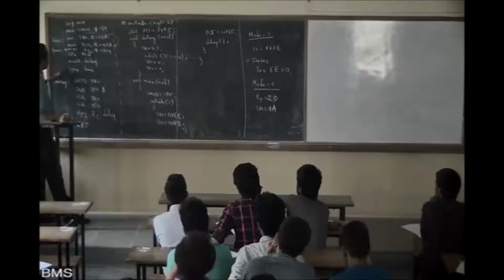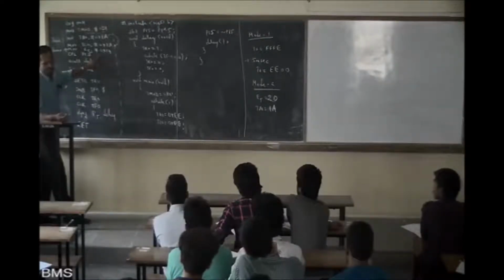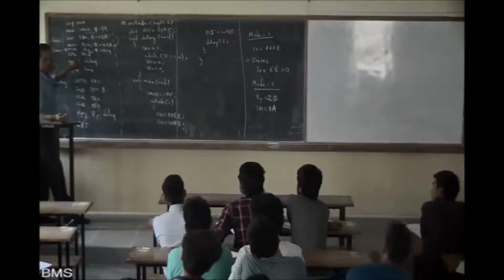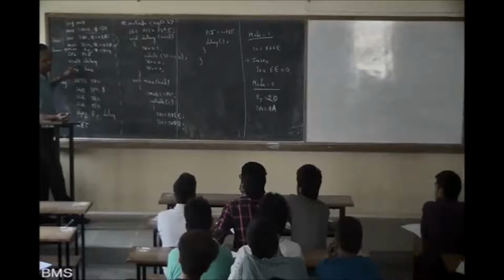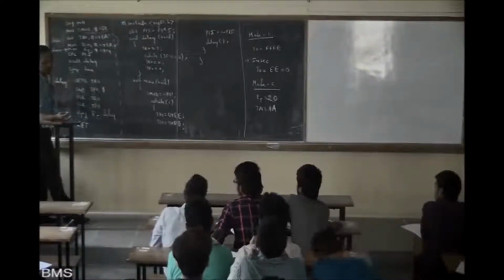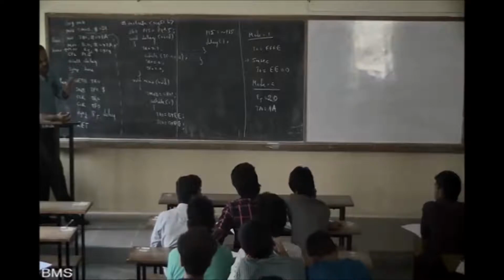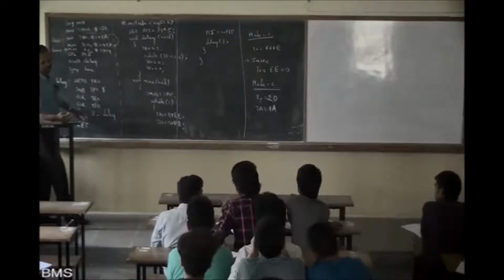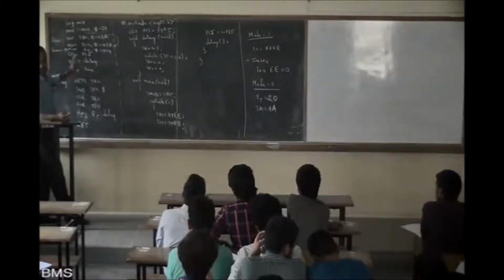Now once we come back and jump here, I have to load R5 again. Load R5 again, then complement it, then call delay. In the delay what I am doing is starting and stopping the timer 18 times. Sorry, 20 times in this case. Once 20 times is over, I will come back here. Is it clear?